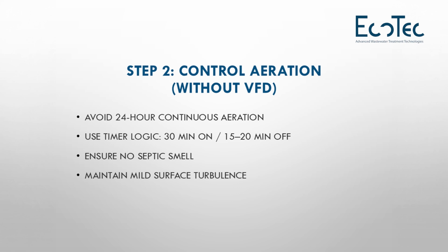What happens when DO probes malfunction, which is commonly happening in almost all plants? What happens when they are not calibrated? What happens when the sensor reads incorrect readings? Blind reliance on dissolved oxygen-based aeration control has become one of the key reasons for plant failures.